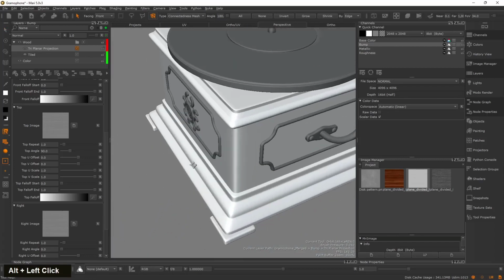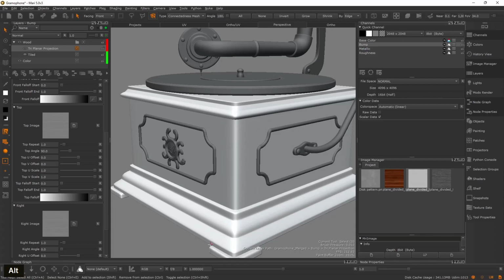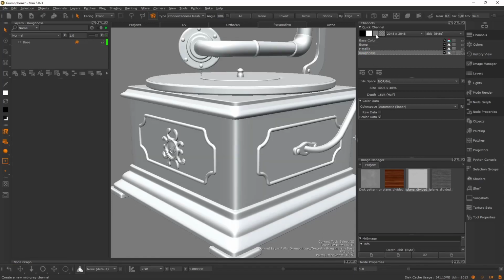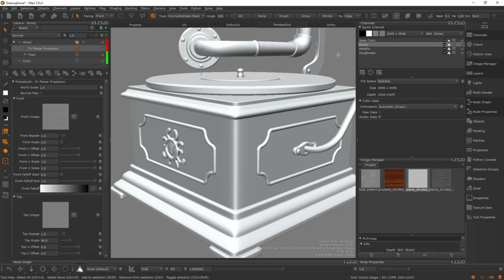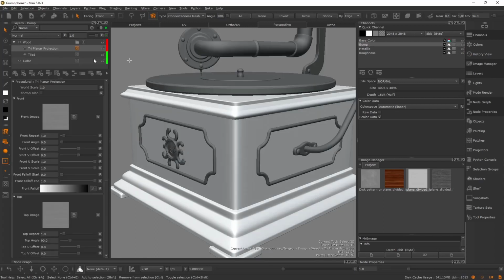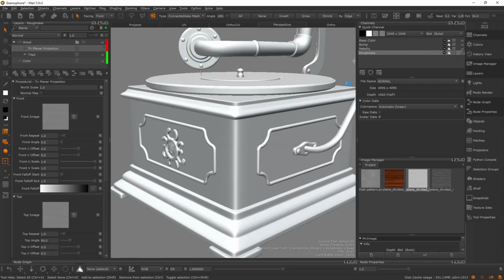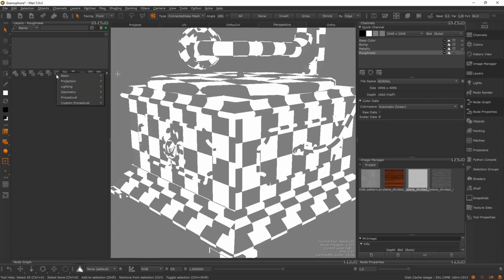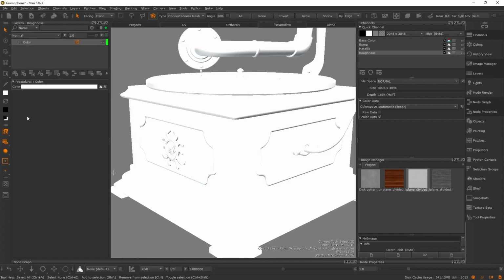All right, let me get rid of this shininess by going to Roughness, Channel, and up here, now it's going to create another channel. So inside the Roughness channel, as you can see, the bump channel contains some layers, but the Roughness channel is a whole nothing. So let me add a basic color, a white color to the scene.